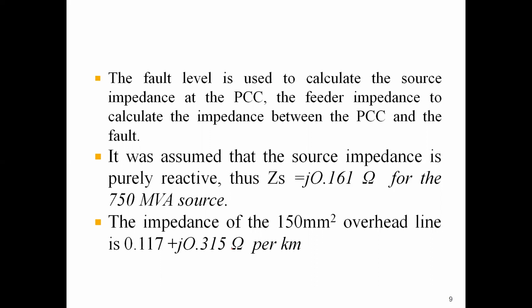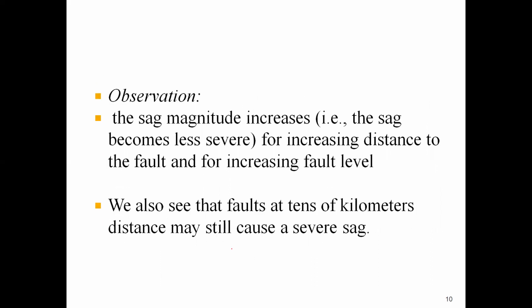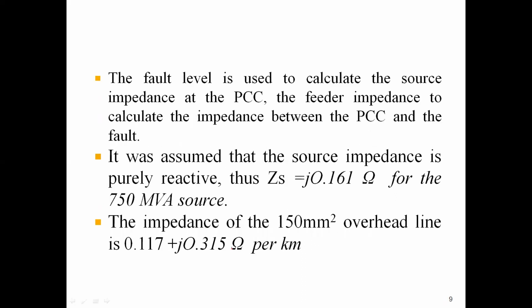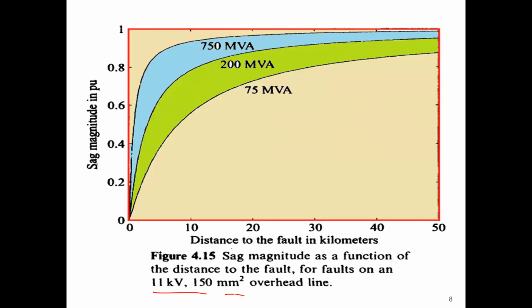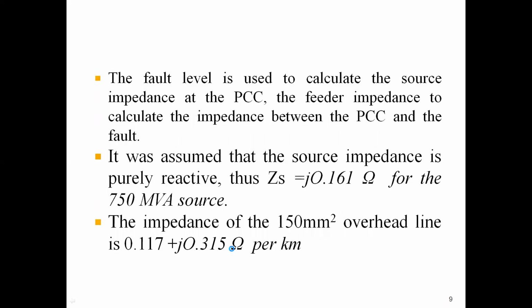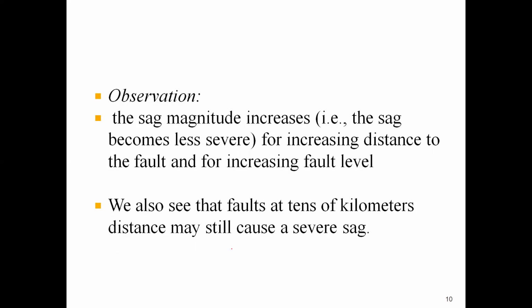Yes, right, very good. The main important observation is that the sag magnitude increases, that is, the sag becomes less severe for increasing distance to the fault and for increasing fault levels. I'll take you back and recollect the observation you're trying to make.